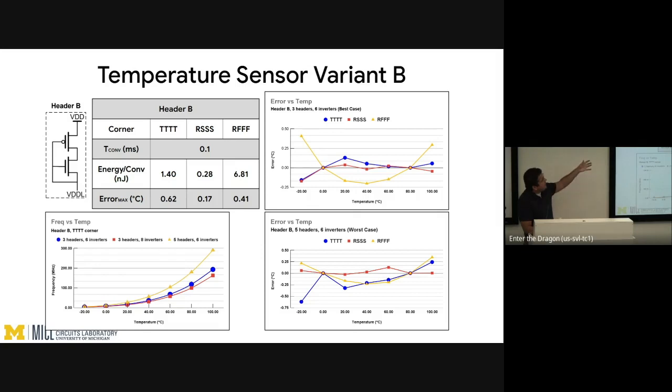The other variant is where the virtual VDD inside the temp sensor has a very low voltage, and that can be prone to variability. So we're trying to get that VVDD to a higher voltage and make sure it is going to function. That doesn't require a lot of work from me, basically only changing this cell here, which is 2 transistors. That's very easy to do, and you can generate multiple variants. You can see the inaccuracy is worse, but it's not bad, it's just below 1 degree C, but it's worse than the other one. The reason is I want to make sure it's working.